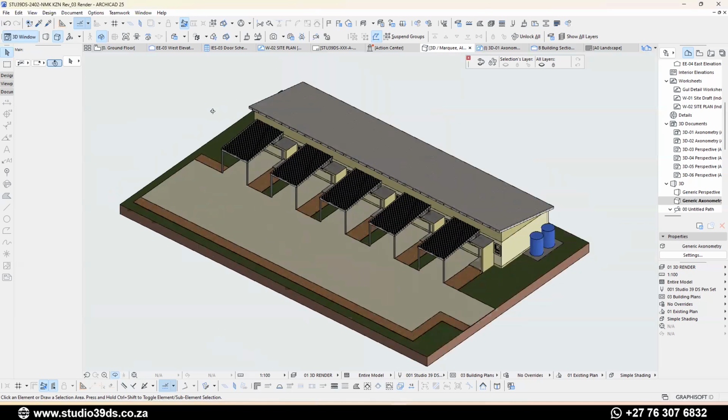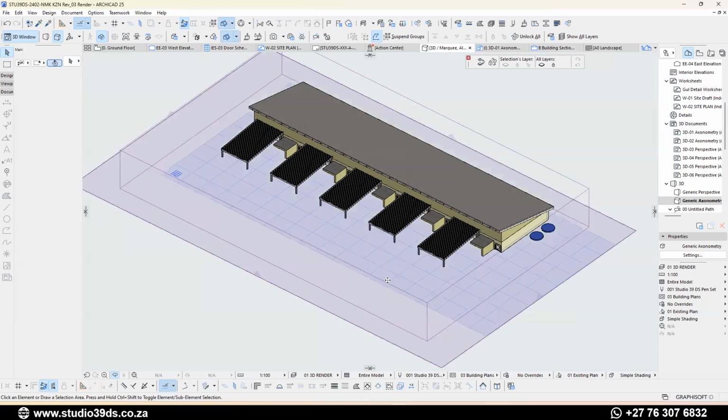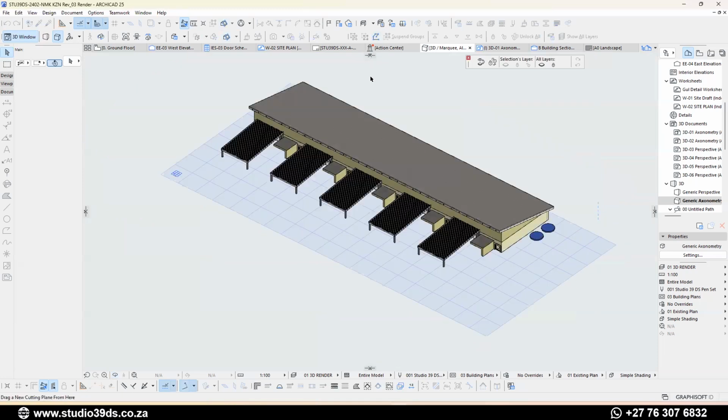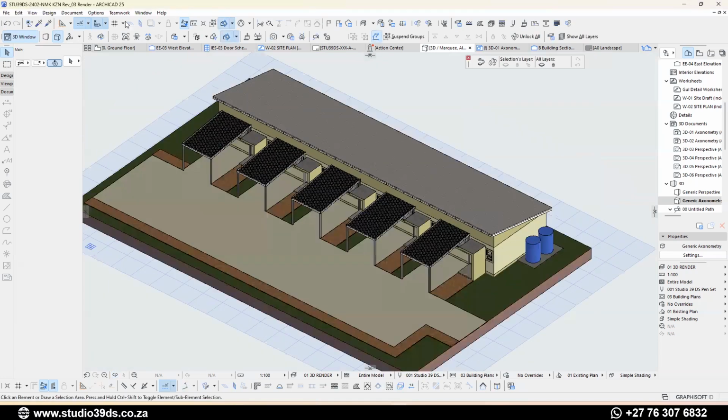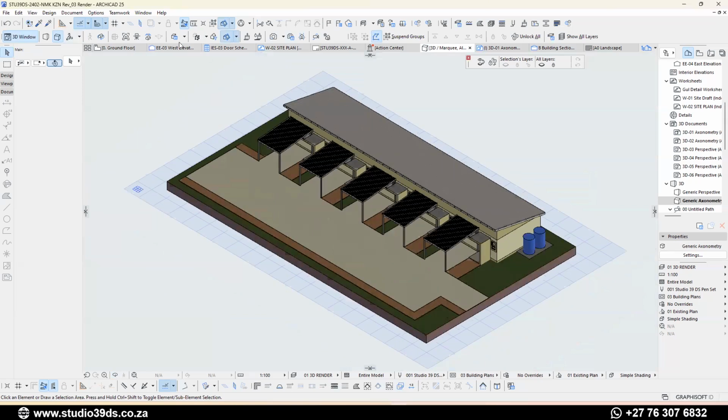The only thing I need to do now is to come in and select the 3D cutaway. As soon as I select it, it cuts. Obviously, there's one that is currently active. So what you'd want to do, since I'm currently in orbit mode, is press O to exit edit mode, and then select this and throw it in the bin right there. So that's it. It worked. Fits everything to the window.